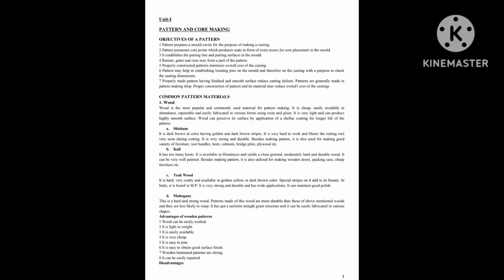Objectives of a pattern. 1. Pattern prepares a mold cavity for the purpose of making a casting. 2. Pattern possesses core prints which produce seats in the form of extra recess for core placement in the mold. 3. It establishes the parting line and parting surfaces in the mold.